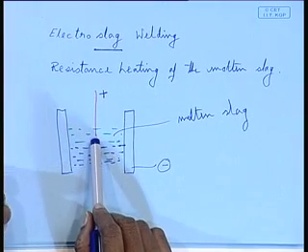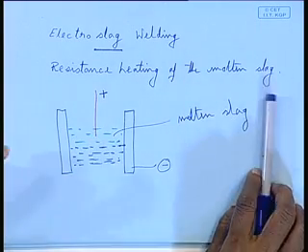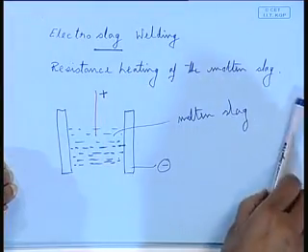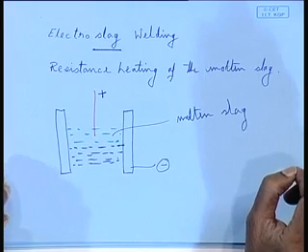What I wanted to say is that in the previous welding methods we got the heat, because for doing welding we are doing thermal welding. So, heat is needed for melting the electrode as well as melting the base metal. It was obtained through an electric arc. A plasma column was formed that generated the heat. Here it is the joule heating or the resistance heating of the molten slag, right. That is how. So, there is a fundamental difference in electroslag welding. The heat source is from the molten slag, the joule heating of molten slag.